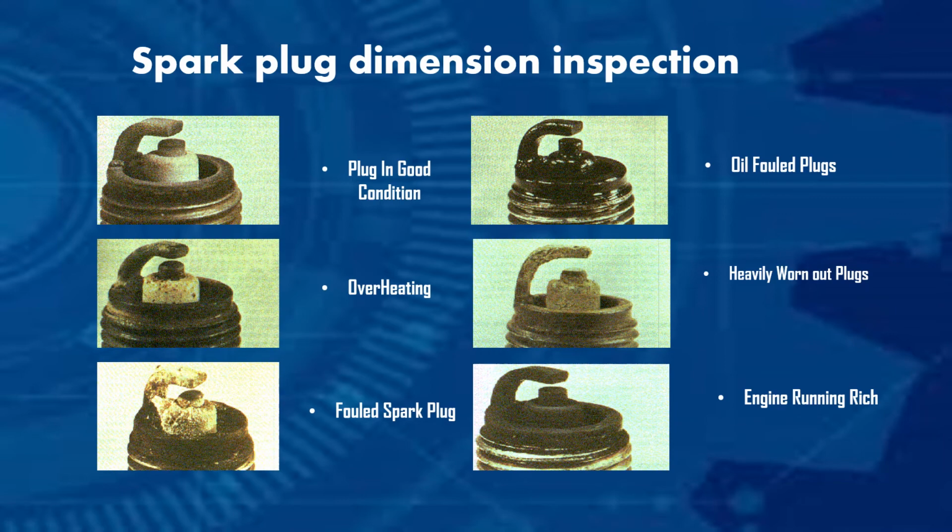Identifying spark plug condition. A plug in good condition at correct mixture and timing will show a good efficient burn at the correct temperature and little wear. Next one is overheating. Overheating of the spark plug will result in a glaze or glassy finish. Overheating is due to a spark plug that is too high in temperature rating for the compression ratio that the motor operates at. Black exhaust, muffler, or catalytic converter. Also, over-advanced ignition timing or cooling system too hot.